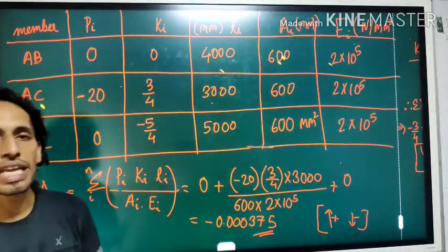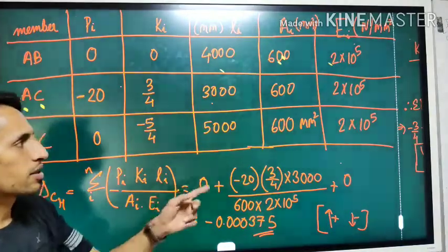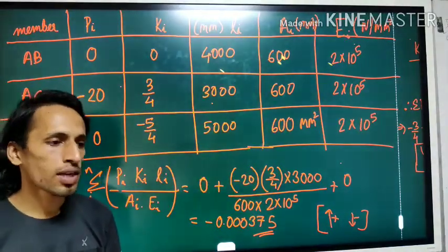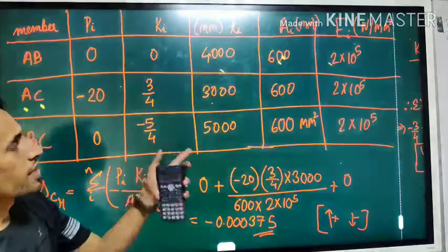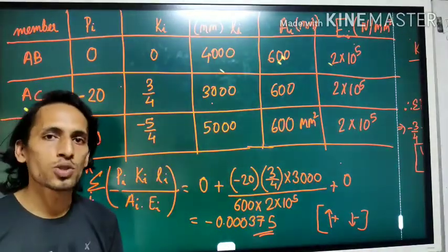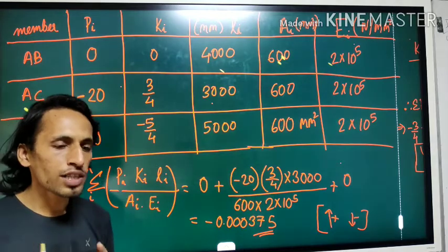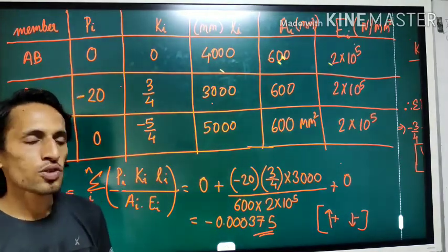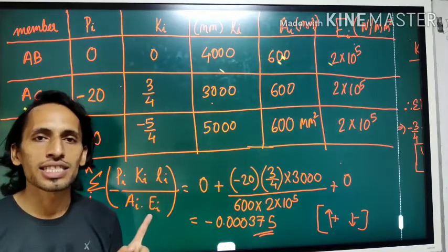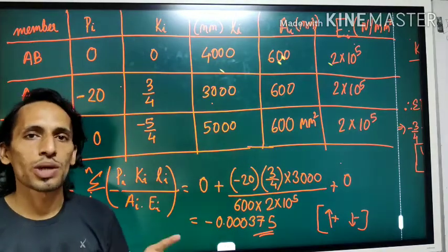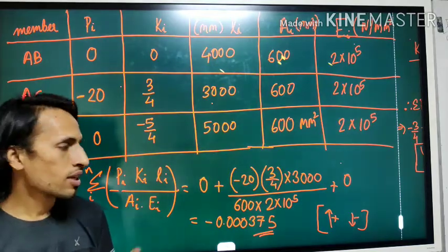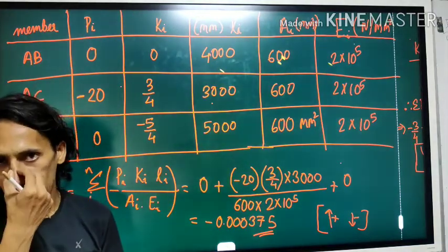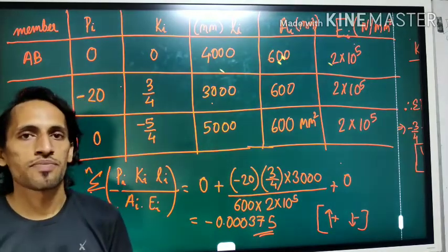So in this way you can solve your simple question, and although you will be required to solve the truss almost 2 times, when you do a lengthier question, you will realize that you can solve it in less time as compared to the strain energy method. So the unit load method will help you to find the value in a faster way.